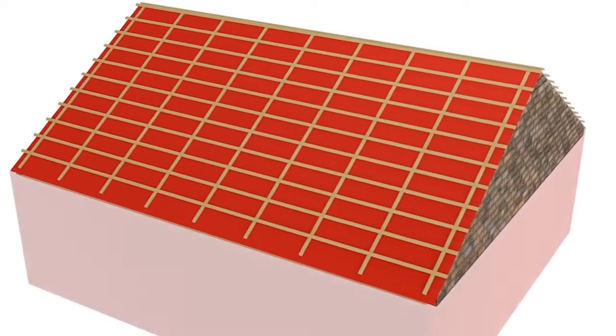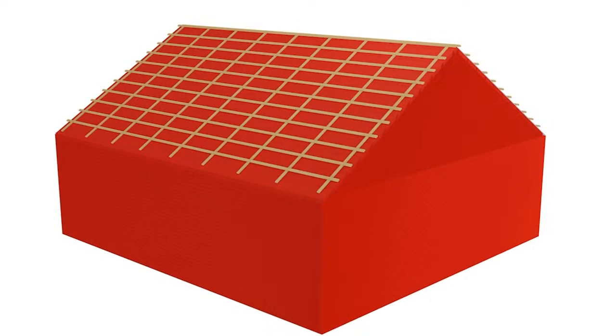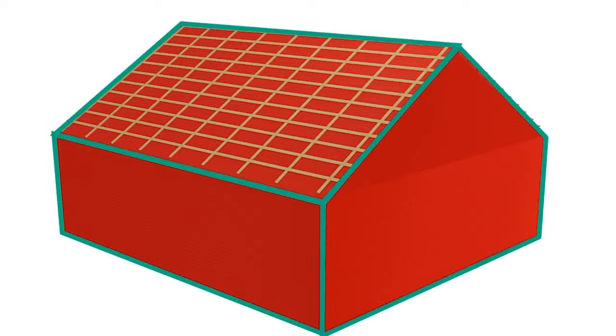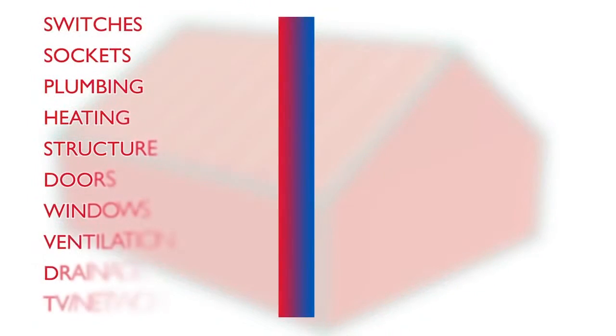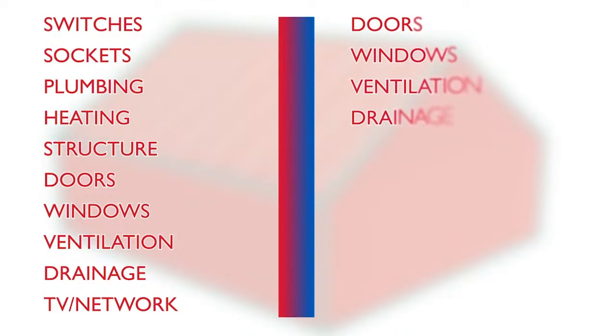If we extend this principle out to the building as a whole, an airtight warm roof construction can be easily integrated into a wall assembly with an external air barrier membrane. We've covered these types of membrane like our wrap-tight in previous webinars, but in a roofing application, this can simplify achieving a good airtight interface at the wall and roof junctions. When internal membranes are used to control air leakage, there are numerous penetrations that must be sealed to provide an effective airtight layer. On the outside of the building, there are far fewer issues of this nature.